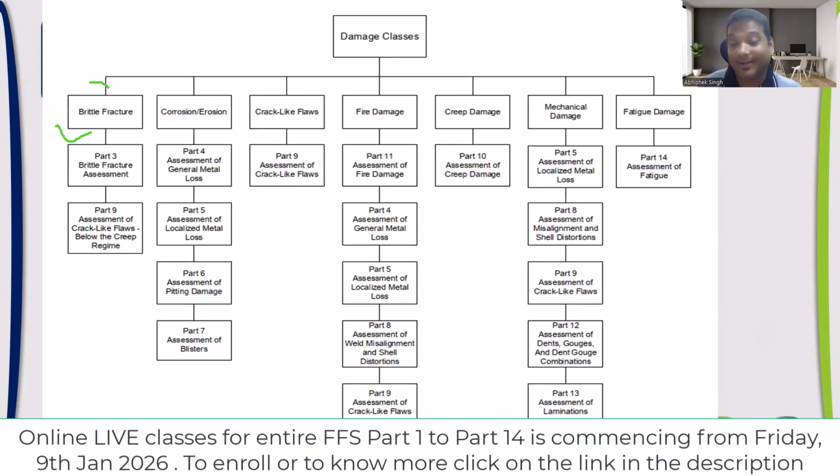Ritesh, yes. MDMT. Okay. So whenever brittle fracture comes to our mind, MDMT is the term which we generally think of. Okay, so it is linked with that. What is the minimum design metal temperature of my equipment? That will decide whether my complete component will be operating in which zone, whether it is in elastic or it has become brittle. Okay, so whether sudden failure is going to happen or not, that is what basically we are trying to assess. So brittle failure is a catastrophic failure, and it does not give us any indication. Okay, and that is the reason it's very, very dangerous.